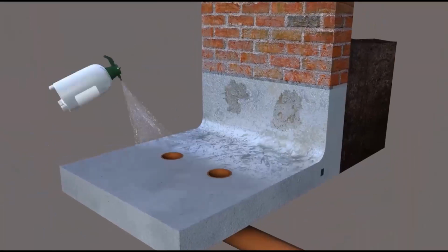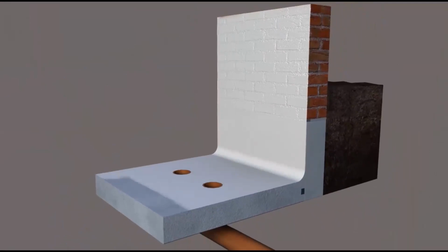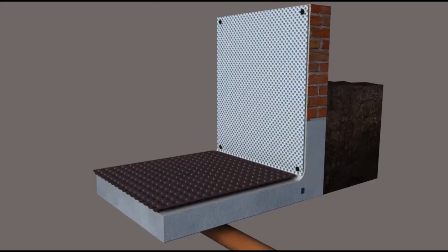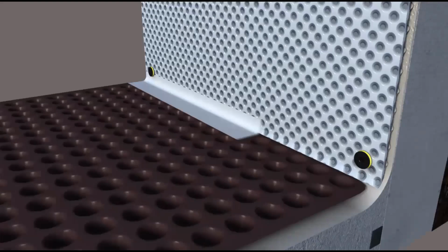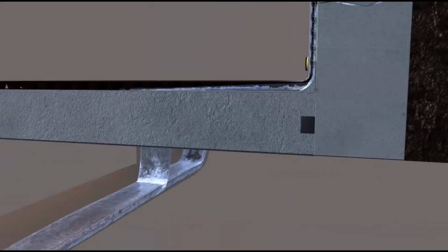We've got an anti-lime primer going on. Remember what I said about the free lime for cavity drainage systems. We've got our cement-based slurry as our Type A system. We've got a channel there if we want a channel for drainage or modular drainage, getting rid of the water, and we've got a Type C system going in. Combination of systems, how to deal with underpinning there.